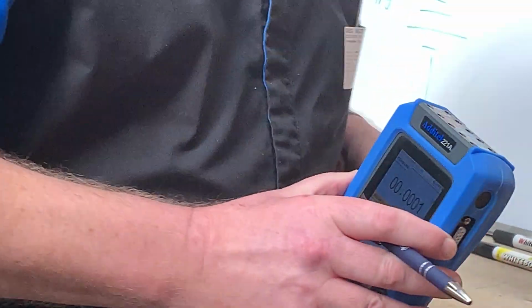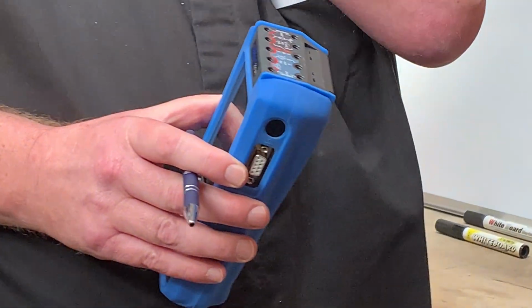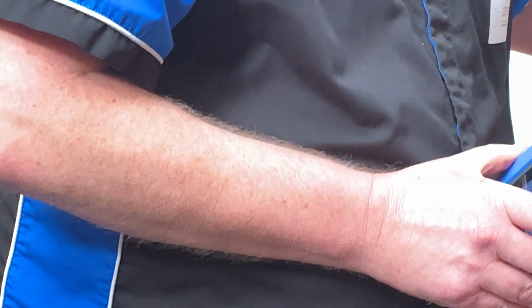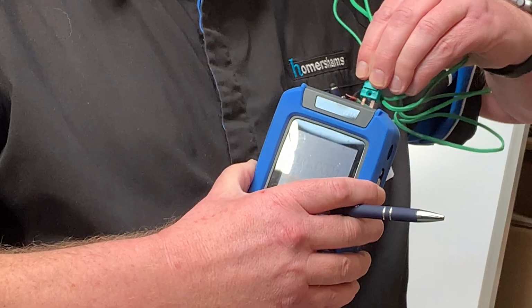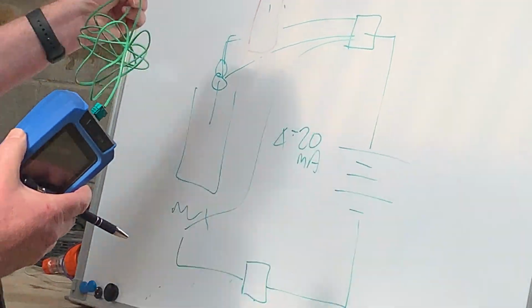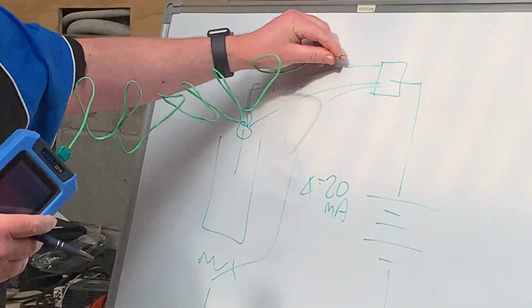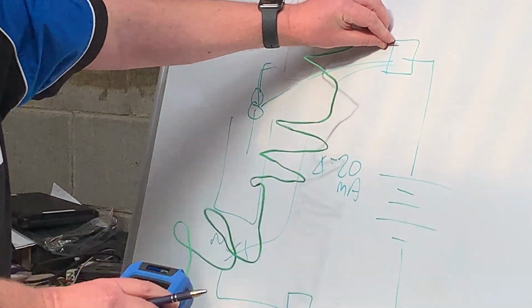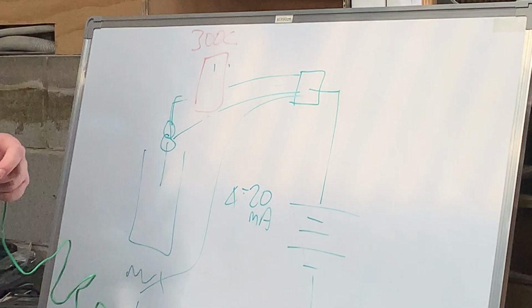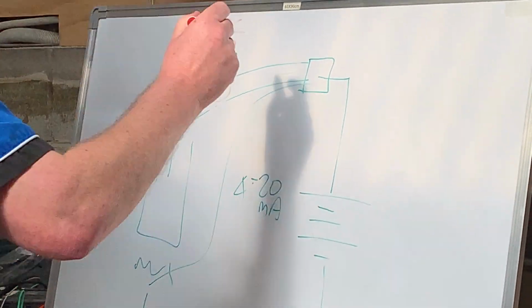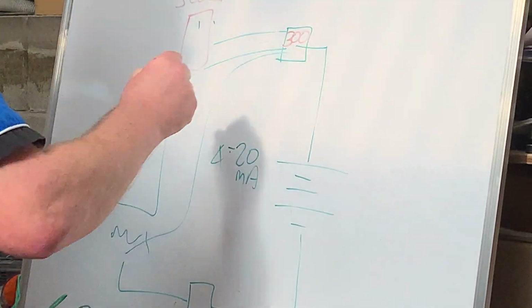So you'd have a lead like the ones, oh, I left them behind accidentally. Oh me, oh my. So you take a lead like so, plug it in the right way around, connect that in place of where the thermocouple was, or perhaps into the controller. And of course, straight away, what you should see on the screen, if it's a standalone controller or a PLC with an LCD, you should see 300 degrees on there.